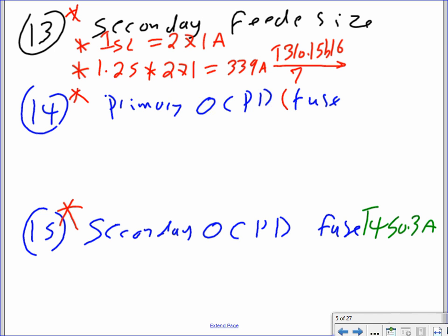310.15(B)(16) under the 75-degree column. Why did we go to 310.15(B)(16), Karen? Because the voltage is 480, and that's the table they use if the voltage is 600 volts or less. Gentlemen, how many conductors do I need now? If you go there, you're going to find the size is going to be 500 kcmil.